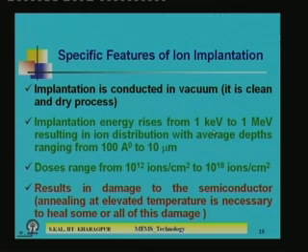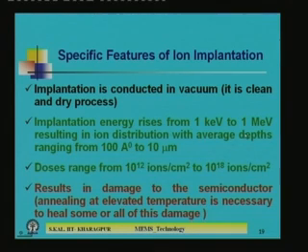So nowadays shallow junctions are all made by ion implantation, it is not possible in diffusion. On the other hand, if you use high energy ion implantation in the range of 1 MeV, you can get higher depth. So in SOI devices, that is silicon on insulator devices, normally high energy implantation is required, those kinds of things you cannot get in case of diffusion.